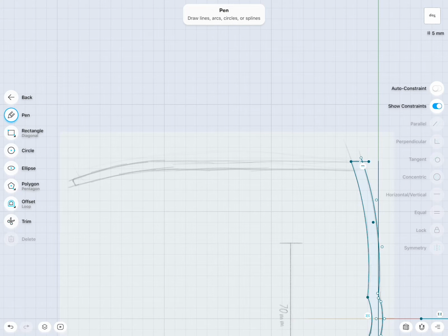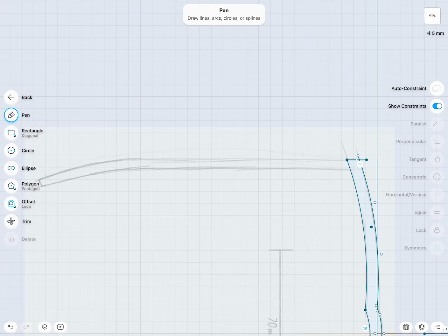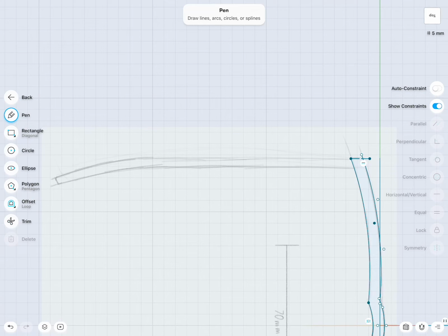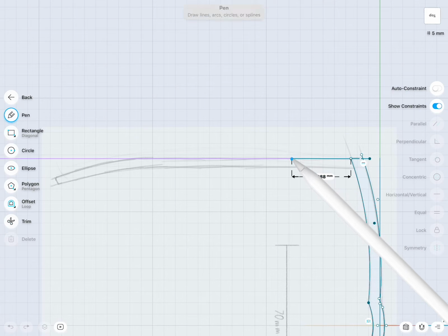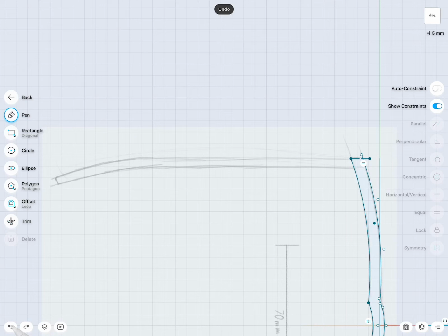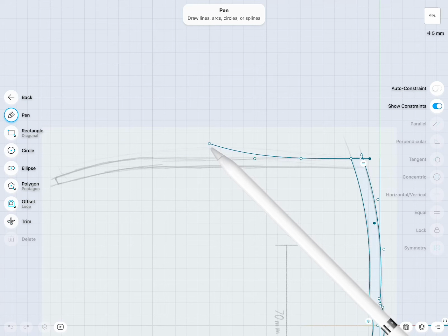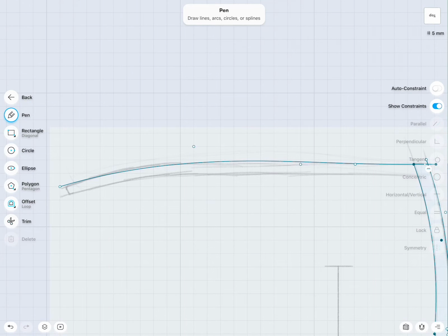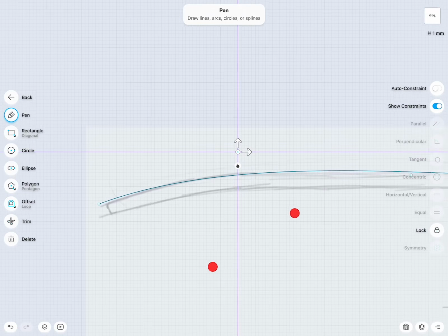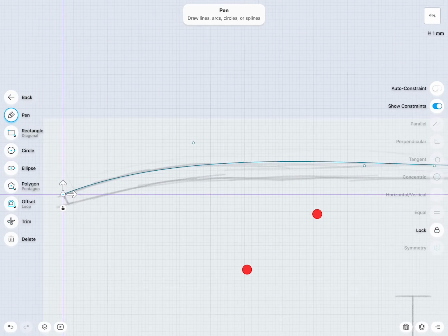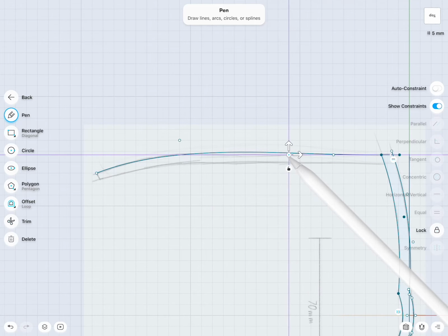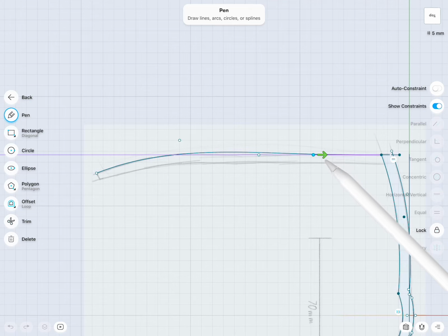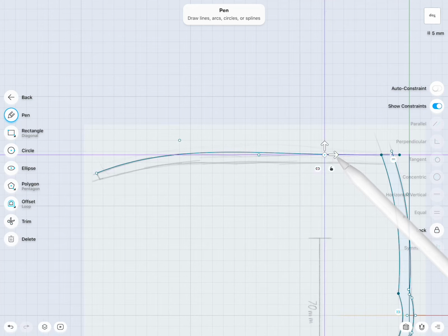Instead of making just a straight temple, the way I drew it, I want this one to go straight and then arc out a little bit to actually contour the skull. So this means the control curve, 1, 2. I need 2 or 3 points in a line to make a line, and I can go up and go down. You always want to try to get your details with as few points as possible, because the more points you have, the more work you will have to manipulate everything, and the higher the chance you also introduce a little bit of chaos into it, or unevenness with the curves.